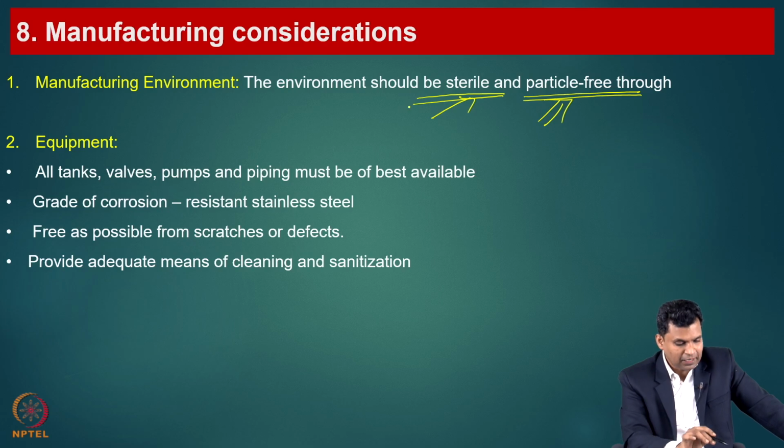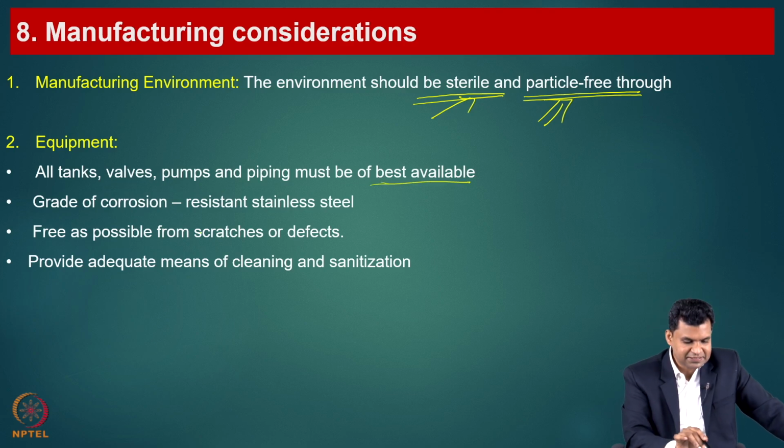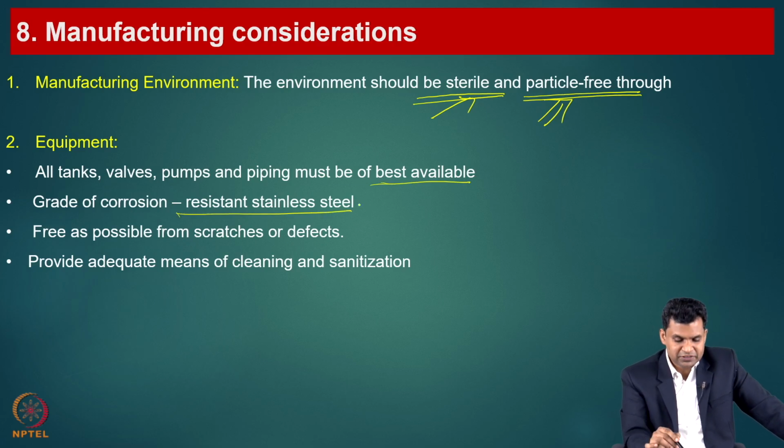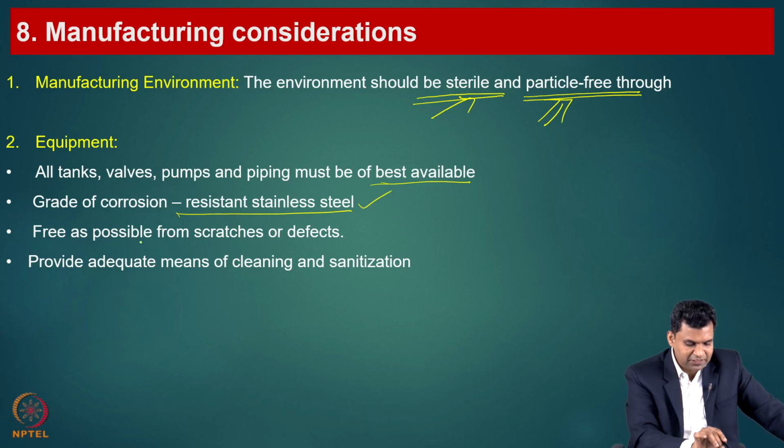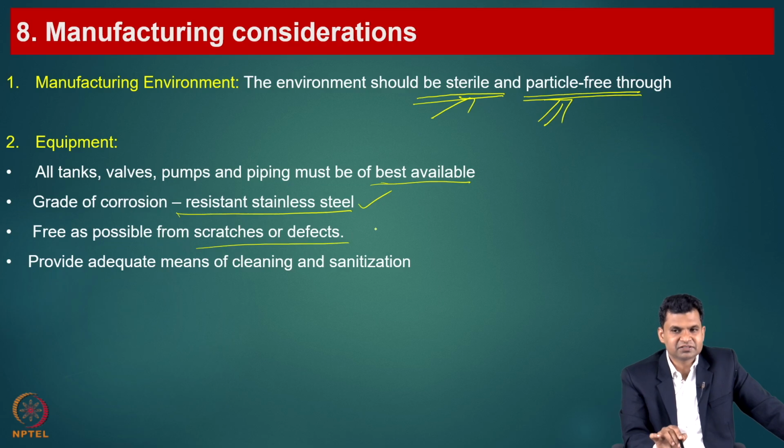And equipment, all tanks, valves, pumps and piping must be the best available, and should be resistant to corrosion. They need to be selected high quality as per the standards and guidelines, as free as possible from scratches or defects. Those defects lead to contamination. If there is a scratch on the surface, particles will generate and settle on those scratches, and that leads to contamination.